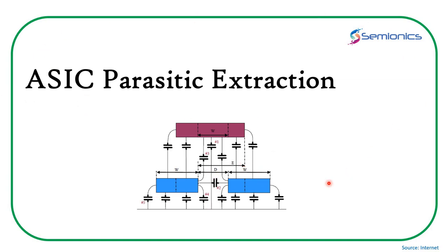Eventually, once the layout is done, you verify it for DRC and LVS and all of that. And when you do the parasitic extraction, that's when you actually get to know how good you have done the layout. That's from the layout designer's point of view. From the circuit designer's point of view, he or she would get a reality check: this is how my design would perform based on the parasitics, when you design a circuit in a particular technology.